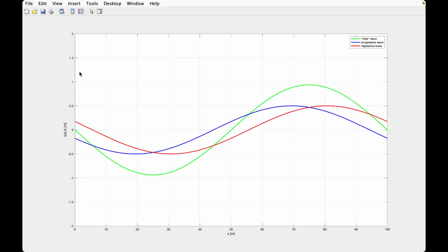It is less because there are some voids, some empty spaces. And so we are calculating the mass per unit length, paying attention to the effective area. And if you are calculating the propagative velocity, we are dividing the tension in the cable by the mass per unit length, but the tension is the effective area multiplying the maximum sigma, multiplied by the load factor with which we are using.